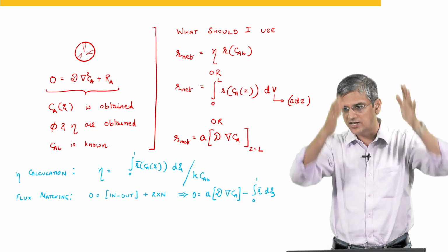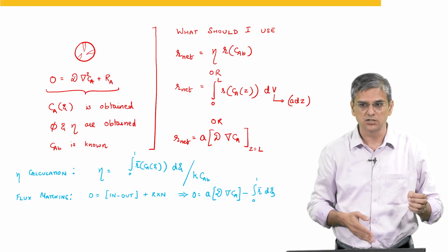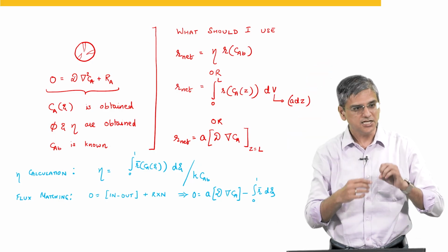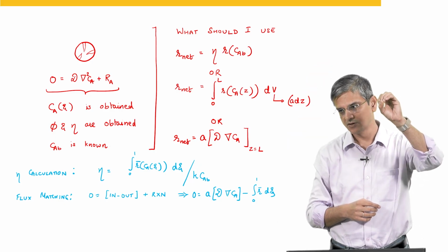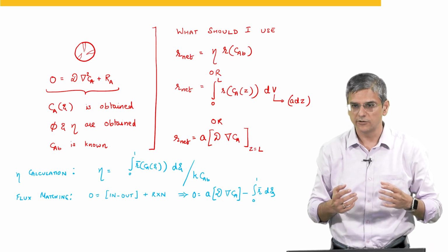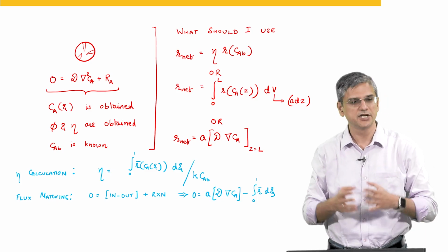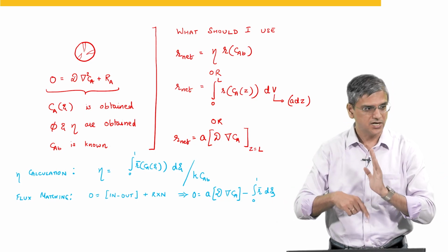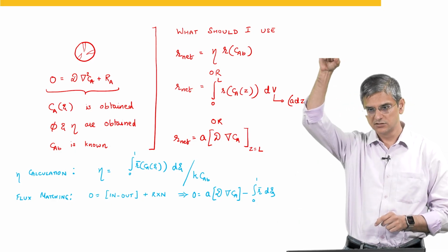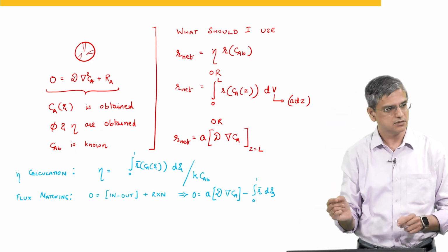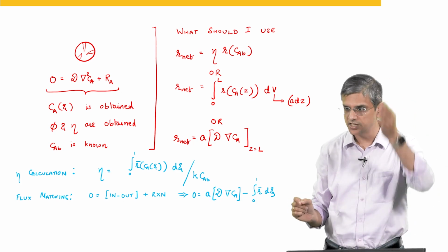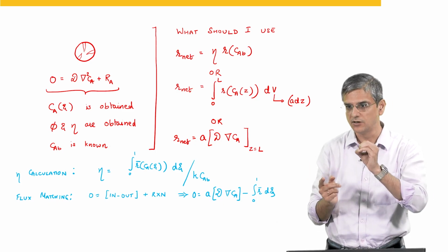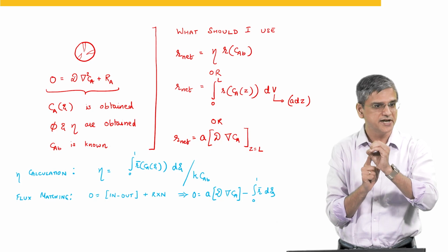What we did was we had one reactor model where the concentration was changing from the bottom of the reactor to the top of the reactor, and at each location we had a pellet model. Okay. These models are called 1D plus 1D, 2D plus 1D, or 3D plus 1D models, because one dimension is varying along the reactor. Okay. So, Z and R it might vary. So, it might be 2D in the reactor domain, and each pellet might be a 1D model, which is a separate 1D model that is varying along the radius of the pellet.